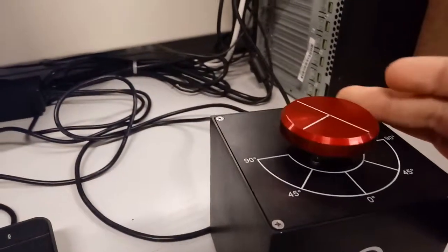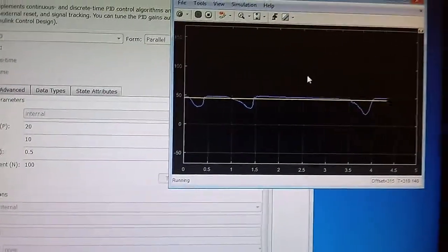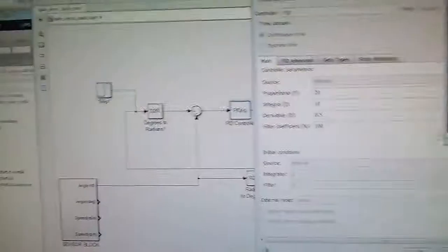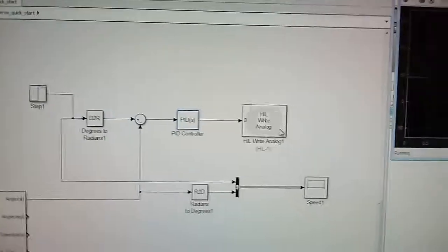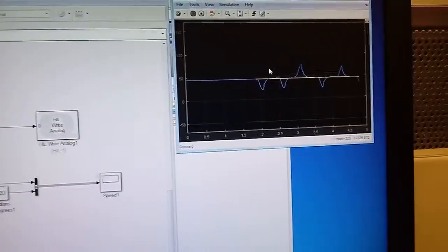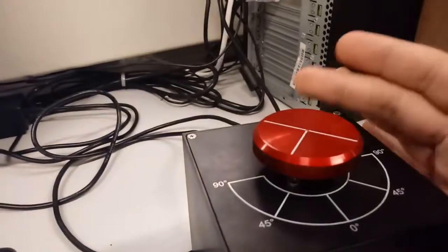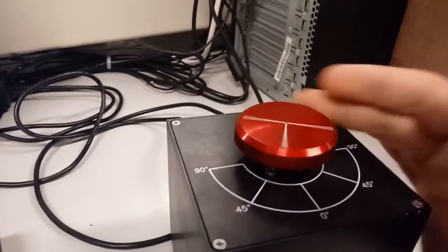With the derivative gain, moving the motor is much more difficult. You can sense the resistance, and it's also visible on the graph. Increasing the derivative gain to 1, for example, will make it converge even faster. This seems to be the most perfect position control system.